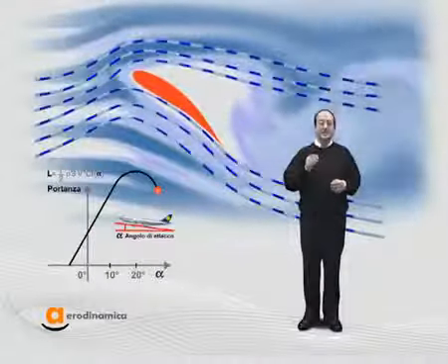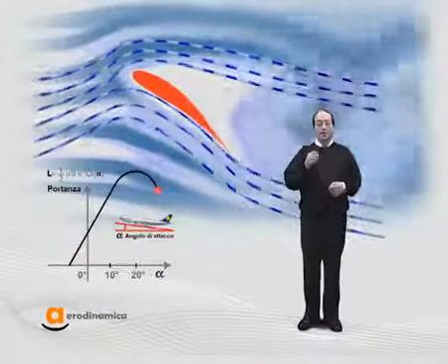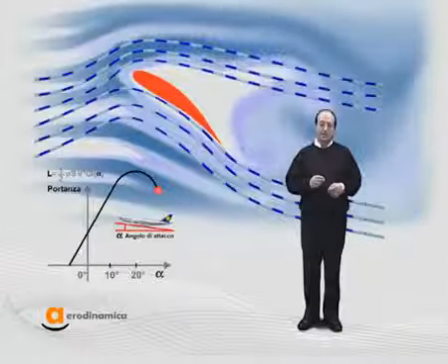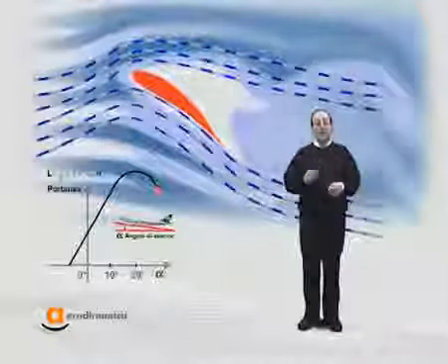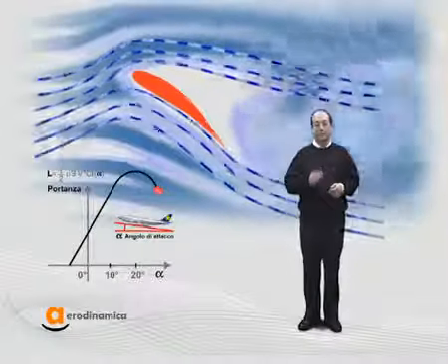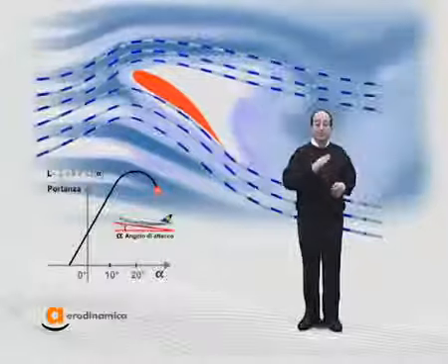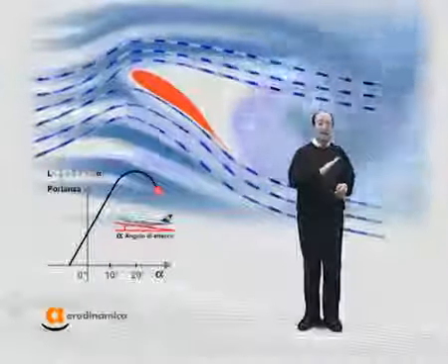The stall is a very dangerous phenomenon for the safety of the aircraft and the passengers. During takeoff and landing, the speed is low and the lift coefficient must be high. This means increasing the angle of attack near the critical value.